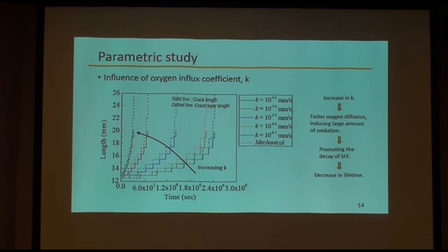Next is the influence of the oxygen influx coefficient, K. The increase in K means faster oxygen diffusion, and it also induces a larger amount of oxidation. So it promotes the decay of the surface fracture energy, and so finally the lifetime is decreased with K.